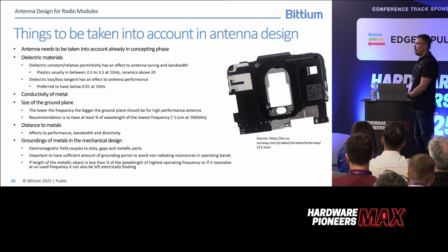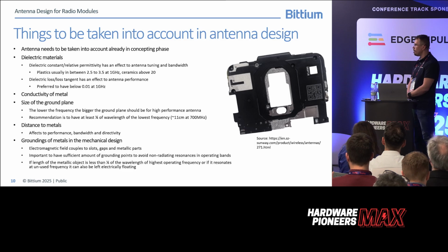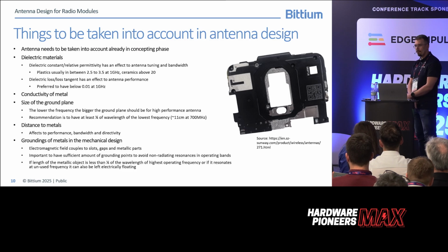So you just direct the radiation pattern in some certain direction, and then you lose the connectivity in other directions. For example, in these wireless routers where you have external antennas like dipoles, if you place it against a metallic wall, it will direct the radiation and then you don't have any connectivity behind that device.